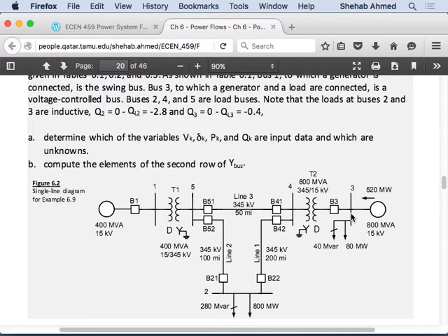If that is the reactive power limit of the generator, that's a special case. That bus will then become a PQ bus, because the load is actually defining the reactive power at that bus. But that's a special case in the power flow simulations, where the load is defining the reactive power at a generator bus. It can happen, but it's a special case.